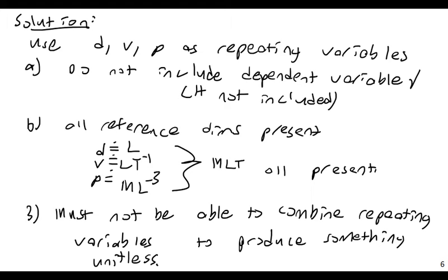All right, so let's solve this using linear equations. I'll let this be my first pi term and look here on the right side of my equation. If you run through that equation for the number of necessary pi terms, I will find that I need 4 pi terms to describe this problem.